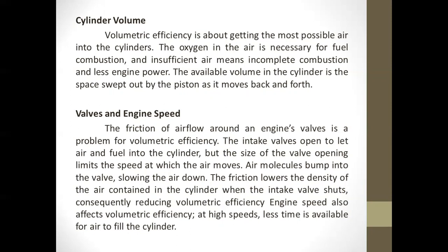Valves and engine speed. The friction of airflow around an engine's valves is a problem for volumetric efficiency. The intake valves open to let air and fuel into the cylinder, but the size of the valve opening limits the speed at which the air moves. Air molecules bump into the valve, slowing the air down. The friction lowers the density of the air contained in the cylinder when the intake valve shuts.